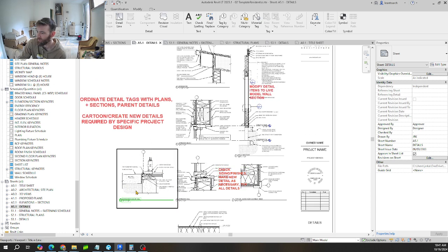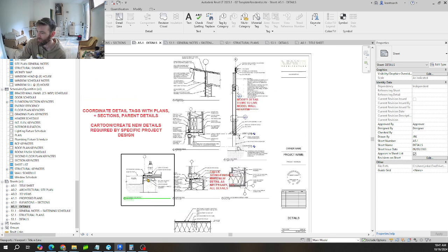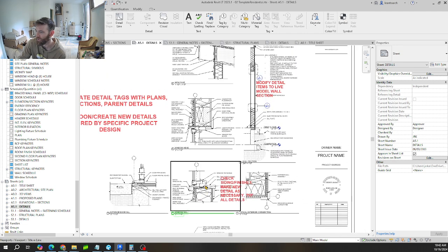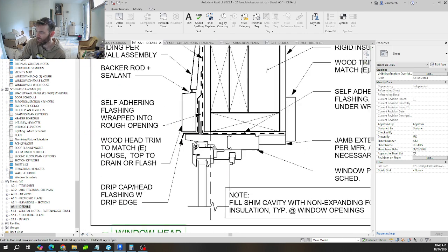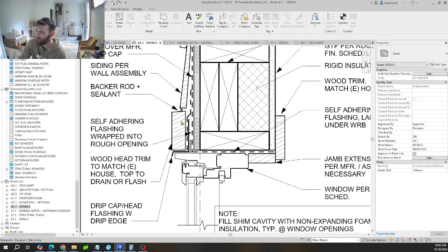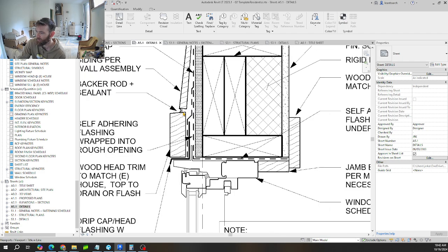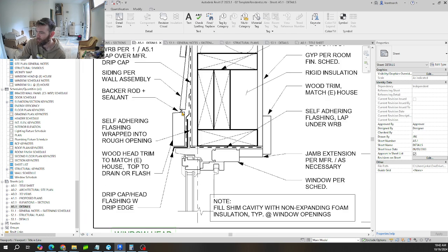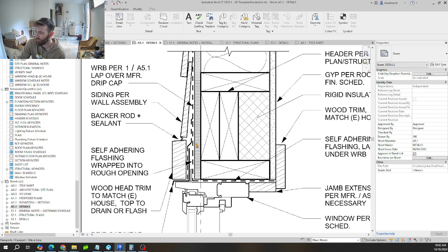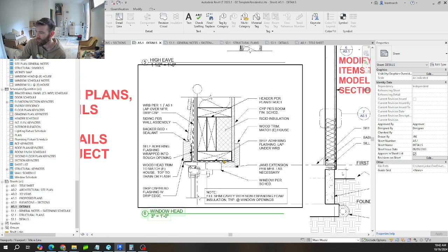You've got to have a door sill, your exterior door sill, because we need water to shed away. And one of the big things architects show is how water is shedding away from a building. So zooming in here, you have flashing underneath your trim, some caulk where the trim meets the siding. You're showing your weather-resistant barrier. That's important to specify in your project.